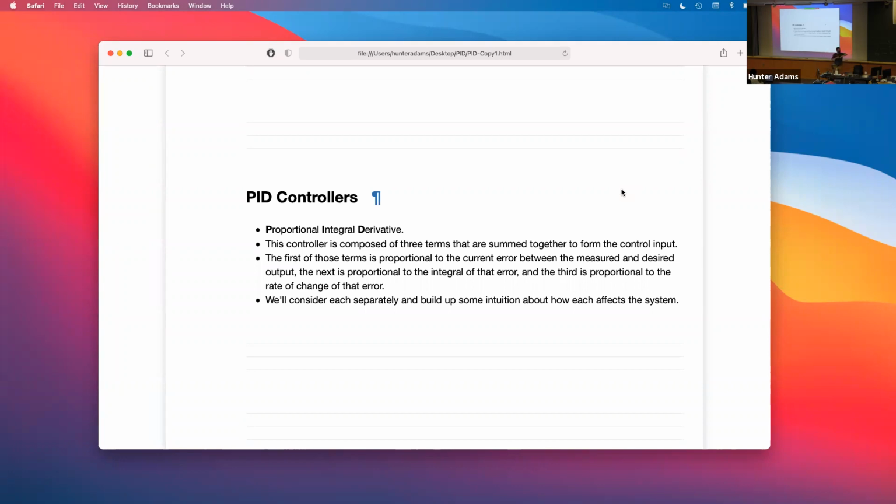We'll look at examples of this. Derivative control looks at the rate of change of the error. It protects you from the situation where we're hanging straight down and we command 90 degrees. The controller sees this huge error, slams the motor on, and starts screaming up towards the desired angle. Without derivative control, you can expect to blow right by your desired angle and start oscillating. With derivative control, it sees that the rate of change of the error is very large and very negative, and it will slow the motor down. So it fights back against the proportional control to limit overshoot and reduce oscillation. You'll see examples of this as well.